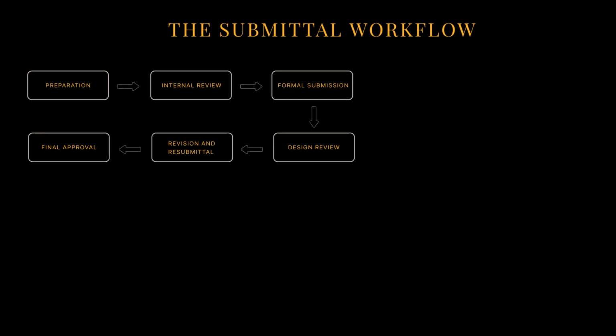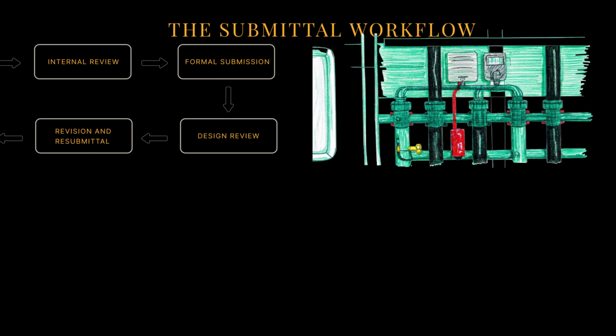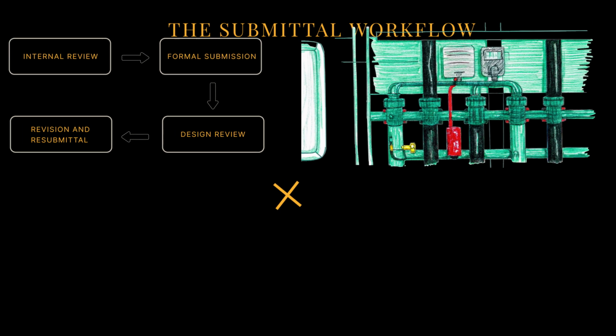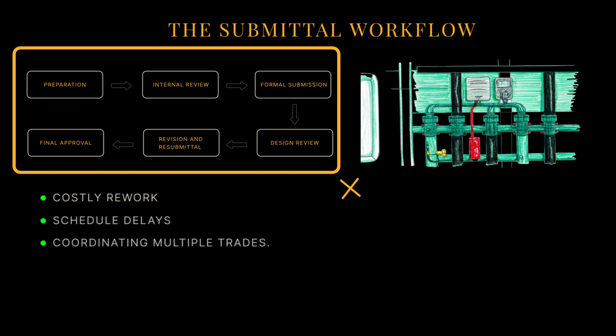Let's apply this to our hospital example. Say you're submitting medical gas piping details. During the design review, the engineer spots a conflict. Your proposed routing interferes with a fire-rated wall assembly. Thanks to this submittal process, the error gets corrected on paper, not in the field. You avoid costly rework, schedule delays, and the headache of coordinating multiple trades to fix the problem.